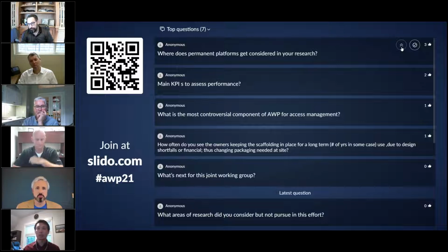One of the considerations that we did talk about was using those alternate means of access. So not just leaving room, not just having scaffolds in as part of the planning, but where can we use an aerial work platform? Where can we use scissor lifts? Where can we use rope access? And on those very narrow instances where it makes sense, where can we just fly a drone and take some high-def video? Because in some cases, that's as good as getting access.